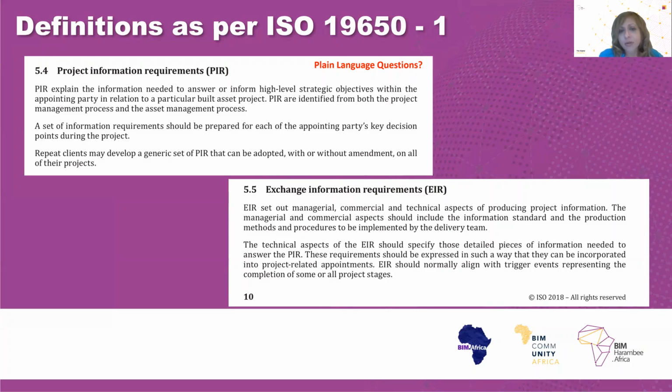The EIR, or the Exchange Information Requirements, contains all of the details of the managerial and commercial and technical workflows and processes that the appointing party or the client wants to put in that particular project, and he or she or that organization also defines all of the information that they want to receive from that particular project.